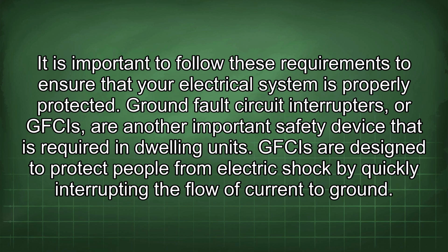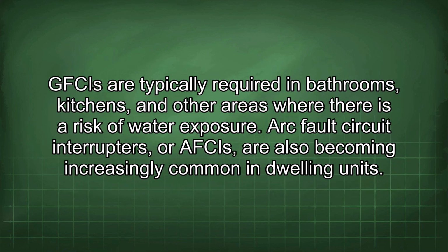Ground fault circuit interrupters, or GFCIs, are another important safety device that is required in dwelling units. GFCIs are designed to protect people from electric shock by quickly interrupting the flow of current to ground. GFCIs are typically required in bathrooms, kitchens, and other areas where there is a risk of water exposure.